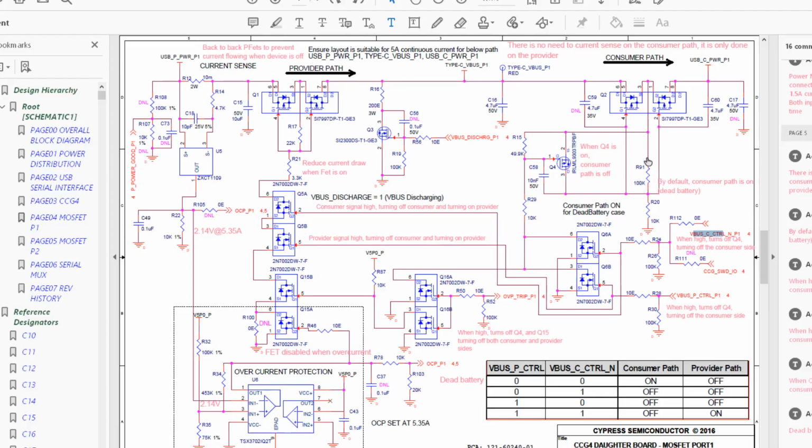And this resistor was acting as a voltage divider from the 20 volts to this point. So it was actually helping pull the gate low. When you're shorting this out, you've disabled the 100K, and you've got 20 volts here, 20 volts here. So the gate just pulls up high. So the voltage at the gate here will be 20 volts because you've shorted out this resistor.